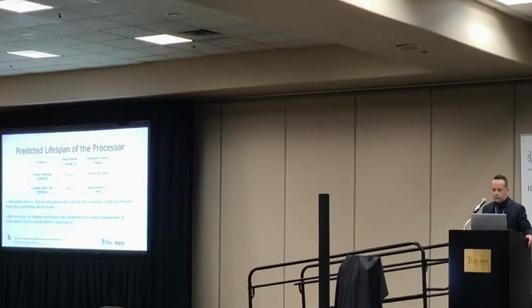And as we see in this table, for normal operation, we would expect that the component would last for almost 1 century, while under thermal stress condition it would be a bit more than 1 year. These numbers comply with what we know from our workshop experience. Of course, for 1 century you don't have to measure the normal condition, but there are computers running for more than 40 years. But we have a lot of failures in laptops near 3 years, which is related to this dust concentration in the heat sink.